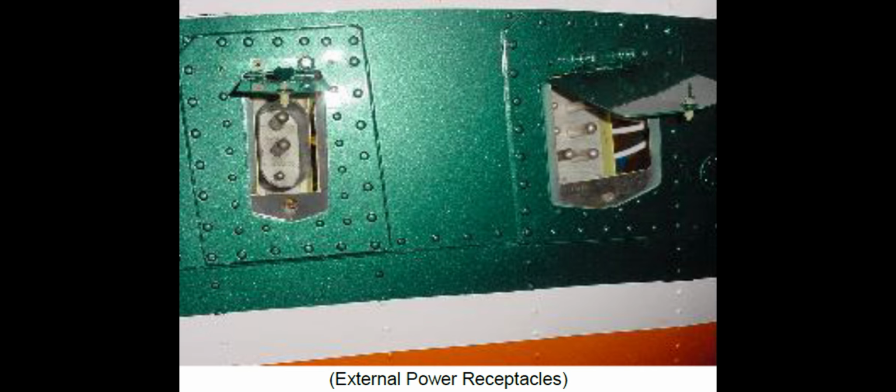External power supply. When external power is connected, a jumper wire in the connector directs 28 volts DC power from the primary DC bus to the advisory panel external power connected light. When the external power switch is placed to the on position, external AC power is directed to the number 1 and number 2 primary buses.